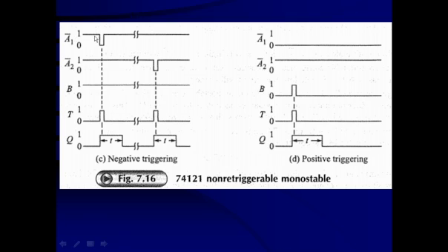This can also be seen in the waveform. This is regarding the negative transition. A1 bar is making a transition from high to low, that is a negative transition. At that time, A2 bar can be anything, high or low, no problem. B remains high. Then the trigger pulse is going to be available, which is changing the output of the AND gate, changing from false to true.